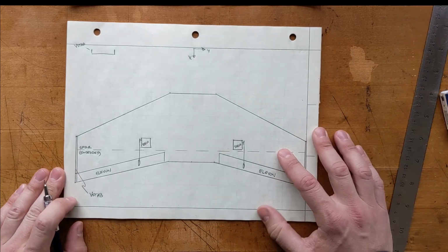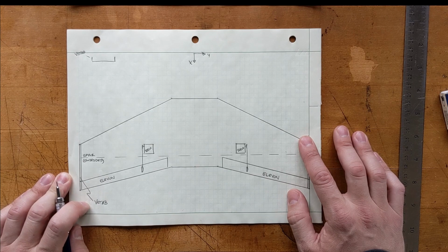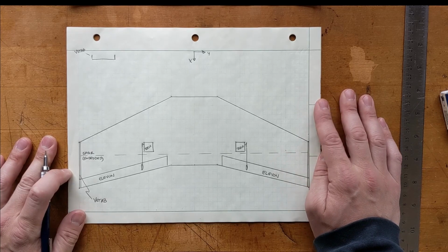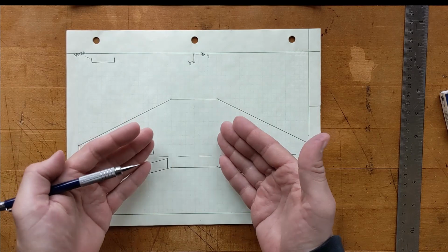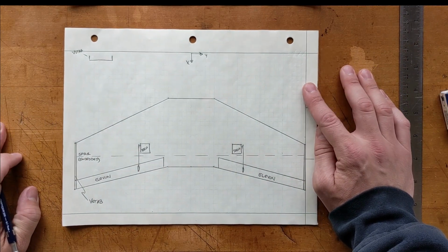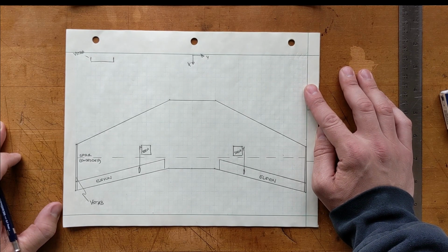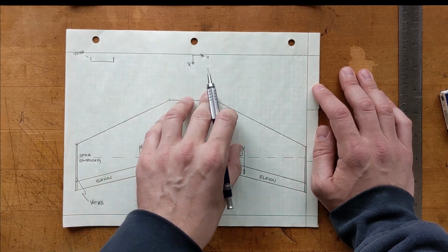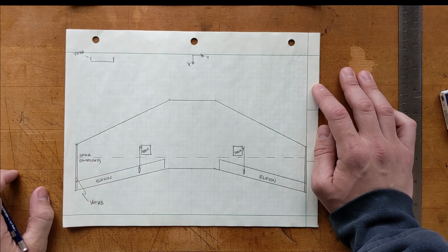We need to add power to this somehow. We need to actually make it go forward and fly. And to do that, we're going to need to add propellers. Now, we have choices about how we do this, how many we can add. We could have multiple propellers. We can put them towards the front or towards the back, maybe somewhere in the middle, the wingtips, all kinds of arrangements. Now, since we're going to be so weight limited, honestly, we'll probably have to use a single propeller. And for reasons we'll see in just a minute, we're going to want to have a lot of space open up front. So let's put a propeller in the back, a so-called pusher prop.